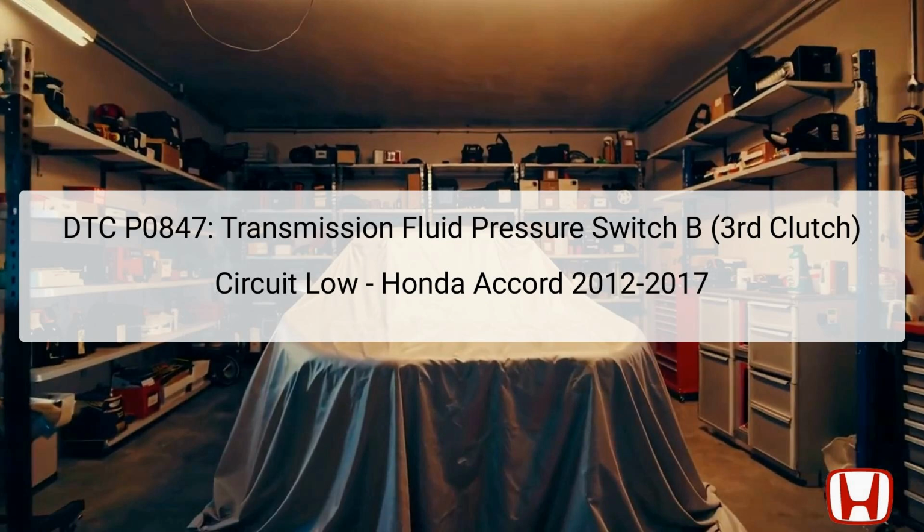The transmission fluid pressure switch plays a critical role in monitoring fluid pressure within the transmission, which assists in gear shift timing and efficiency. It is located in the transmission assembly, typically positioned near the clutch packs. When this code appears, it indicates that the vehicle's powertrain control module, PCM, has detected a low voltage or failure in the circuit for the pressure switch, impacting vehicle operation.